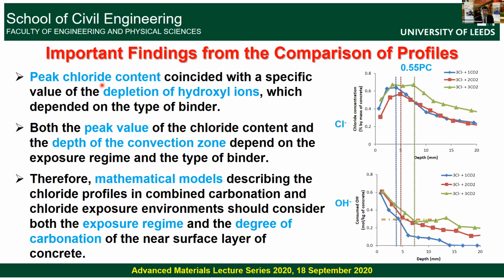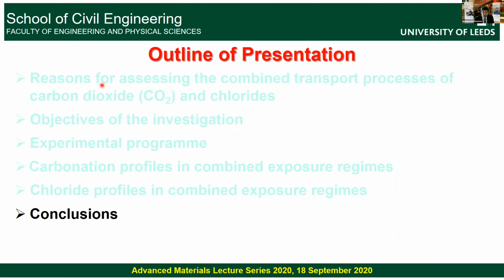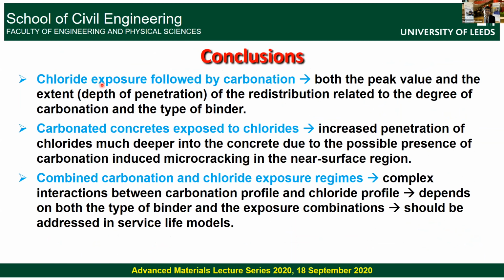Okay. So now moving on to the conclusions. With chloride exposure followed by carbonation, both the peak value and the extent, the depth of penetration of chlorides and the redistribution, are related to the degree of carbonation and the type of binder.